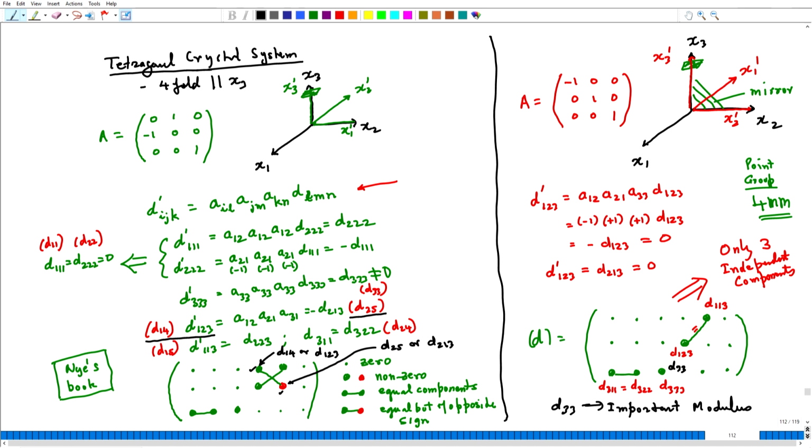Well, in this gas lighter example, when I push the trigger, it actually compresses the piezoelectric crystal. So, it is compressing it in the x3 direction in a uniaxial mode, and therefore, the modulus D33 becomes important and others are not as important, the other two components in this tensor.